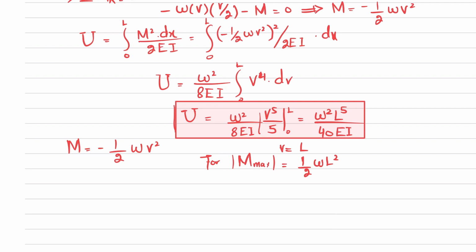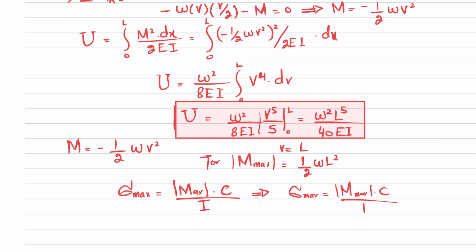From this maximum moment we can calculate the maximum bending stress, which is equal to maximum bending moment into C divided by I.